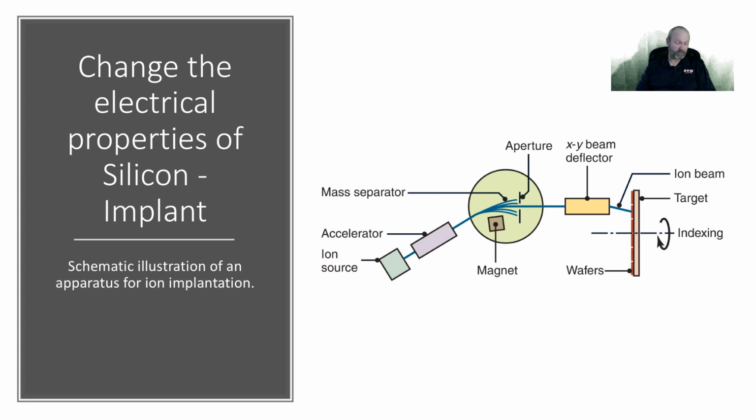But anyway, by implanting the silicon wafer, you can change the electrical properties, because now you're adding a donor, an extra electron. If you put one type of element in there, it has an extra valence electron, so that's free to move around. Now all of a sudden that crystal is no longer a semiconductor, but actually a conductor. If you go the other way, where you put in an element that has 3 valence electrons, then you have an extra hole that things can fall into.